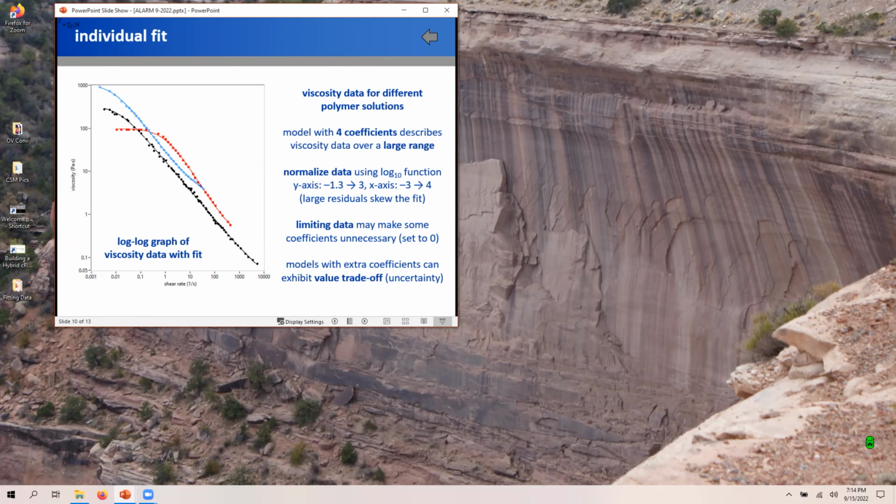I mean, water is typically said to have a constant viscosity, but if you were to shear it at a high enough rate, it would probably shear thin like this. So it would look kind of like the red curve, and then it would decrease and then hit a limiting value, when essentially all the water molecules were aligned in some way. It's insane shear rates.